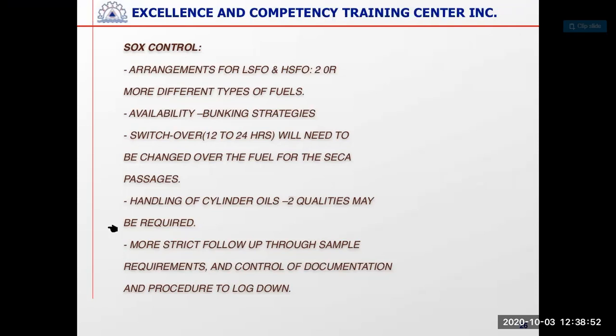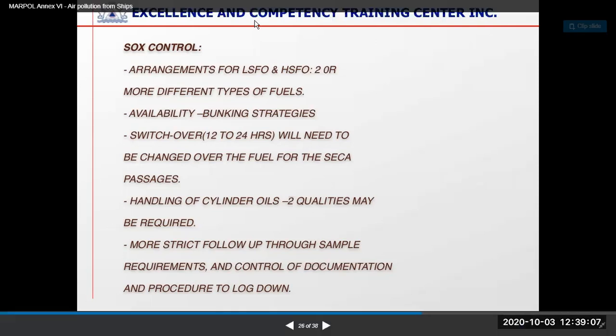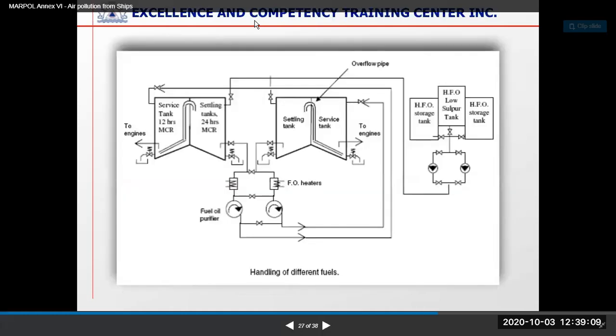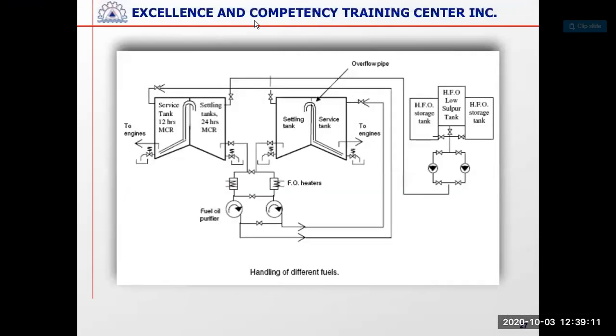Then for cylinder oil also we have two qualities of oils. Then we need to have thorough sampling whenever we are doing changeover. Need to keep the samples and get them checked, proper documentation and logging all the procedures. So these are the different designs for handling different fuels with different service and settling tanks.